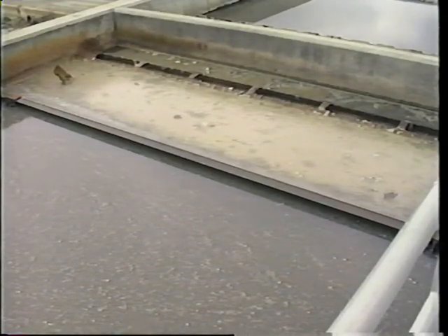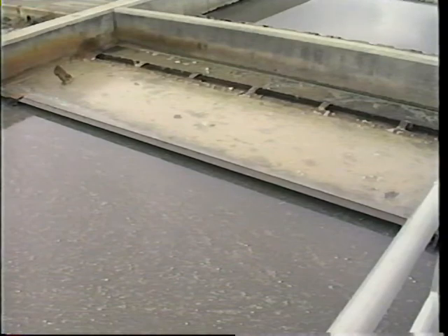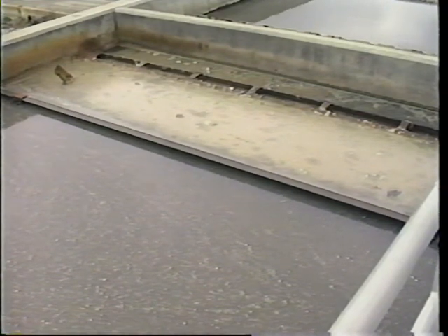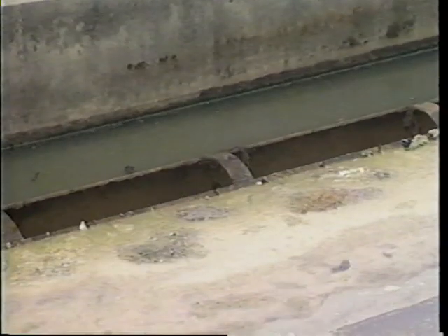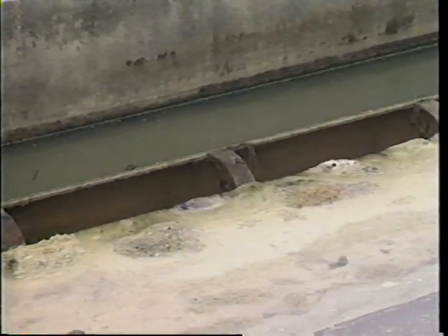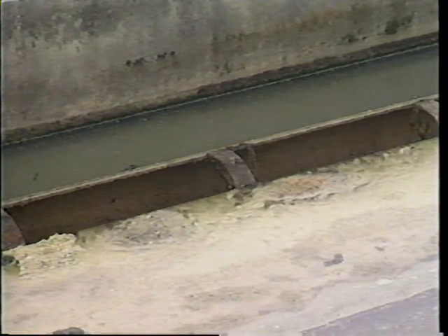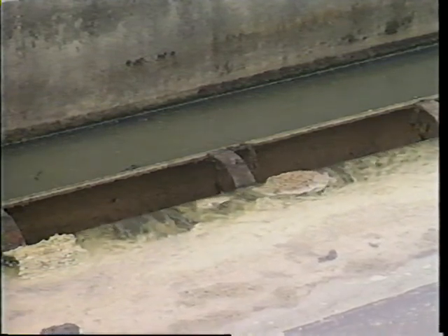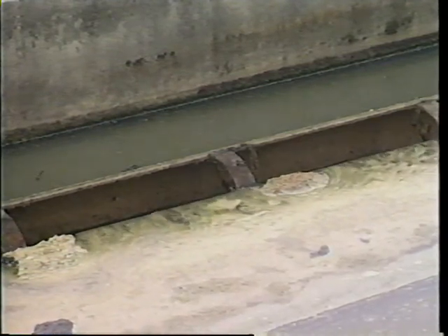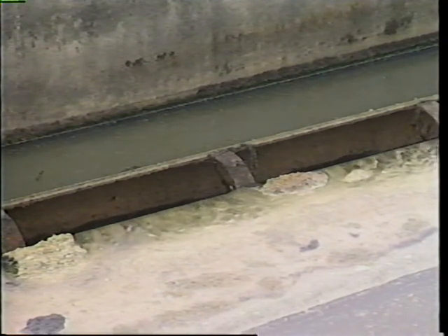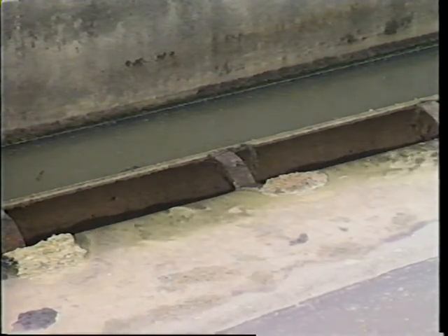Removal of solids will also reduce the biochemical oxygen demand, commonly referred to as BOD. It's the rate at which microorganisms consume dissolved oxygen as they metabolize the waste. Primary clarifiers are equipped to collect and remove biosolids and scum. Biosolids are the settled solids at the bottom of the clarifier, and scum is the unsightly floatable solids which can be skimmed from the surface.